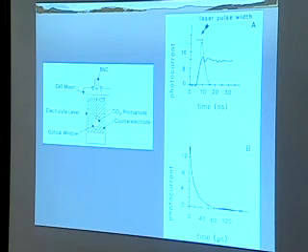The second complication is you have essentially a big-time noise problem. That is, you're looking for a small signal that's time varying over a fairly short time, and you don't have a clean way of getting at that signal. There's lots of opportunities at a semiconductor electrolyte interface to generate noise. And so we made everything coaxial. That is, we have a coaxial wire going in through a BNC connector, and we have a counter electrode here, which is a platinum gauze in a cylinder. And we just cut a little hole in that gauze, and we put our TiO2 electrode right down the center. So the whole electrochemical cell is a coax cell, and that really cuts down on the noise. We carry the coax all the way into the cell. And when we did that, we could get a pretty reasonable signal.